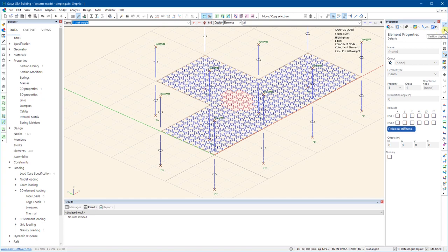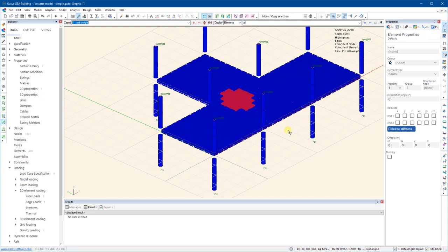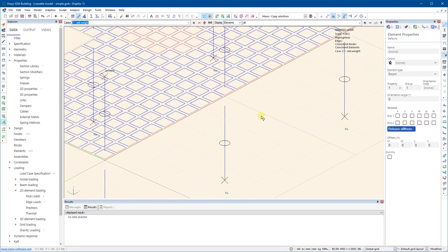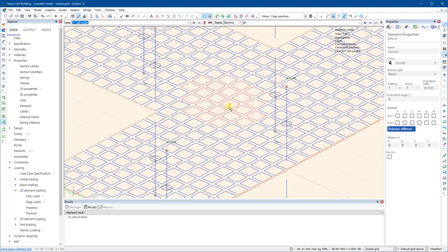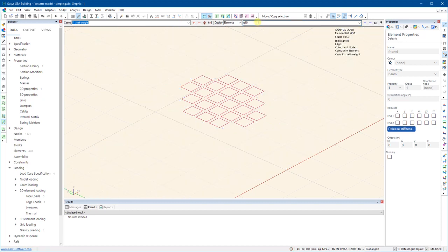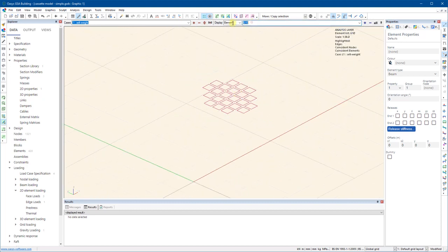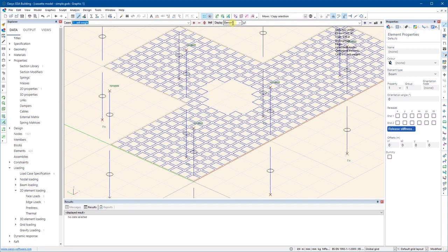If I filled it in, you would see the red elements and the blue ones. If I click this element, you see it's group 10. If I click the blue element, you see it's group 1. In the same way, we can come back to the top. We can go G10, and all we'll see is the group 10 elements. Similarly, we could go G1, and all we would see is the group 1 elements. If I click all to get out of that.